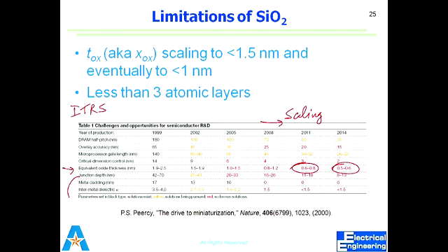We don't have better control of a very thin layer of oxide, because in order to grow a thin layer we decrease the pressure. At low pressure we try to control it, but still we cannot go beyond 1.5 nanometer. And as the scaling chart says, after 2014 we should be having a 0.6 nanometer thick layer of oxide.